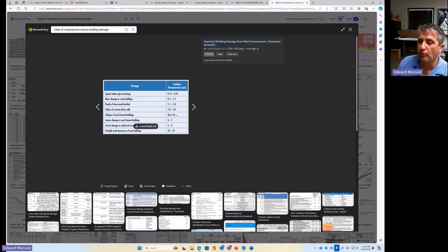If it's in storage, your best detection method, honestly, is going to be a level switch in the sump, because all your liquid is just going to travel downhill. It's going to fill the sump. You've got a level switch telling you you've got a level where you shouldn't have a level. And that's the best way to know that you have a spill.